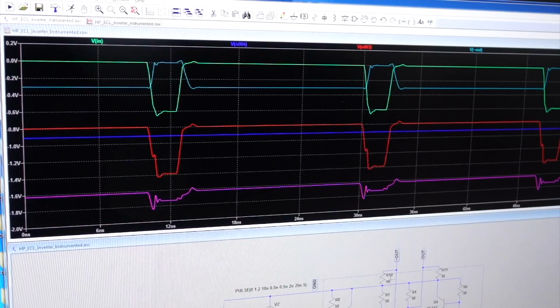Question is, is the instrument also going to load the circuit with an additional 50 ohms? I did not think about it, but I'd say quite possibly yes. If so, I should double the voltage swing of the circuit.